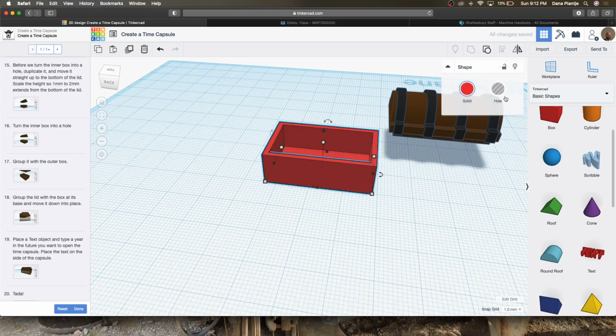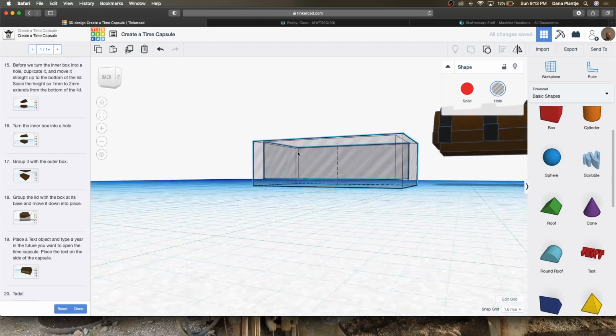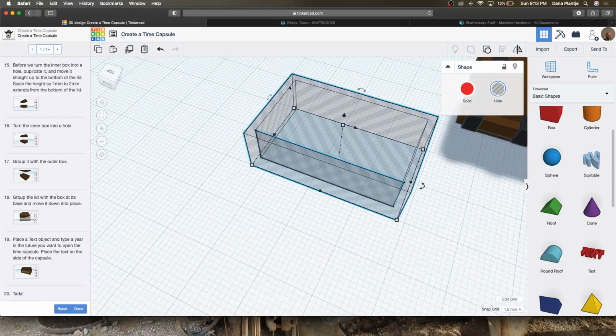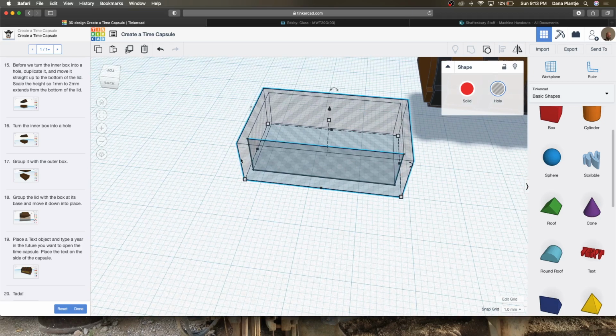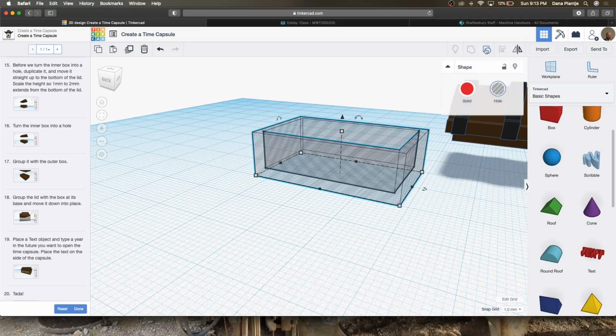sides so that the opening of the object is going to be centered and uniform all the way around the walls at the bottom. I could set it so that this wall thickness becomes smaller. I could set it so the wall thickness becomes bigger, but all I would need to do would be to change this object that I added to the bottom of my lid, my little notch, so it matches the interior opening so that the lid fits snug with the base.